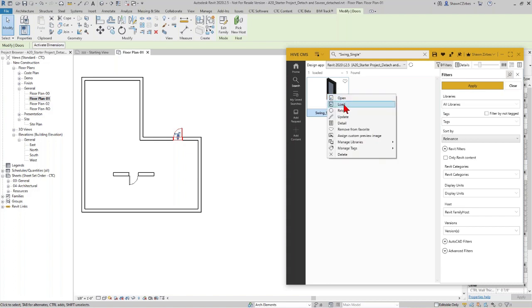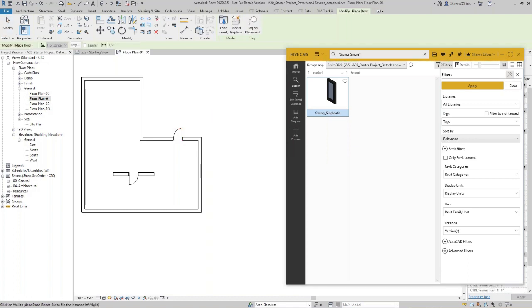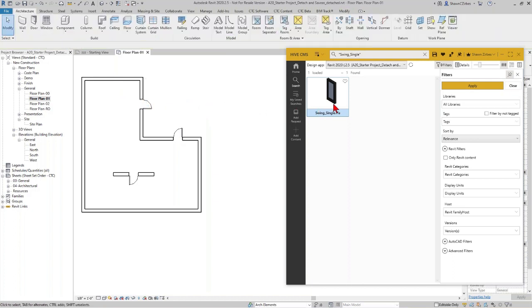Well, there's load. In the case of Revit, load is the stock double-click action. When I double-click it, it loads it, and if it's already in here, it uses it. That's what load does. In fact, if I click load right here, it will do the exact same thing it did when I double-clicked it. It just checks to see, is it the same thing? Oh, it is. Don't prompt anything, just use it, just move on, right? Well, now there's a new option here on the right click, reload, okay? That's another function.